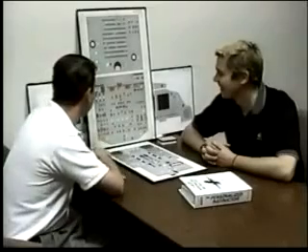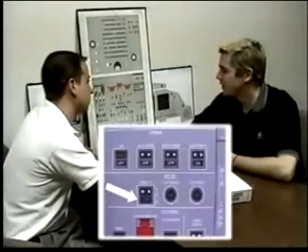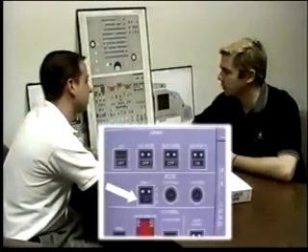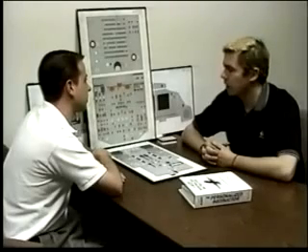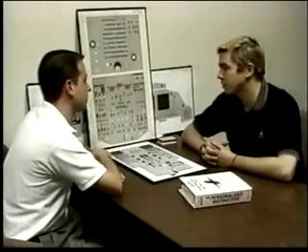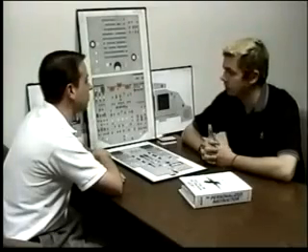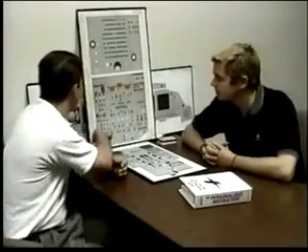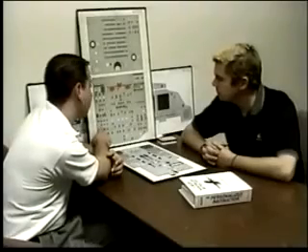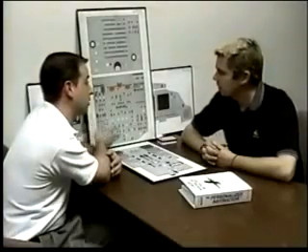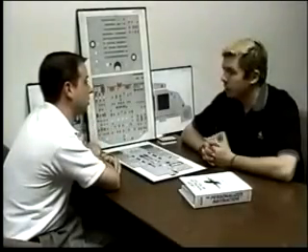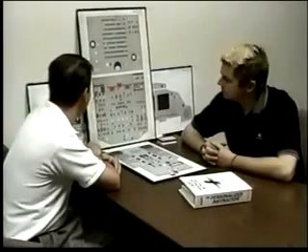Why would you select the ground control switch to on? Because the FARs require us to record with the recorder from the reading of the first checklist. Since the automatic portion of it shuts off after 5 minutes, and we read the checklist prior to the first engine start, then we have to turn it on for us to be able to record it. When you select it to on, what happens when you start the first engine or after first engine start? It reverts to the automatic mode and the on light extinguishes.